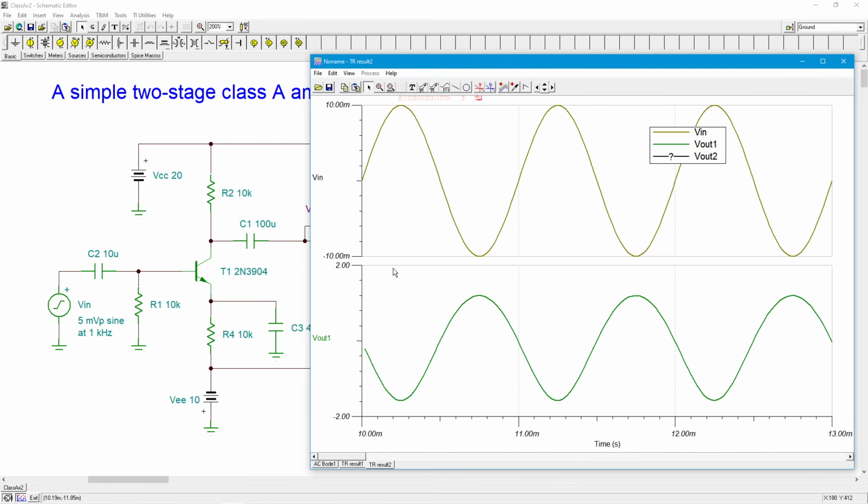On the other hand, when it's at the other extreme, small signal, that's small current, that's a big R prime E, meaning we get a small gain. And that's what's happening here. We're not getting enough gain.